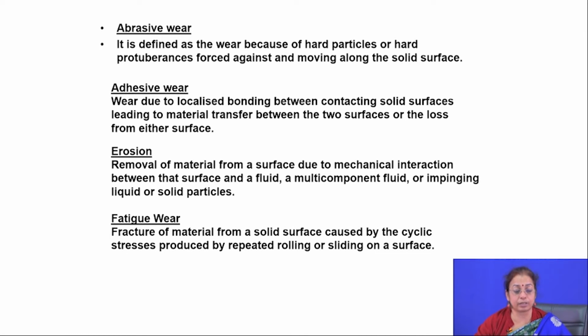Now, quickly I will go through each mode of wear as well as sub modes in this particular talk. Now, if you talk about abrasive wear, it is defined as the wear because of hard particles or hard protuberance forced against and moving along the solid surface. So, when a hard surface moves over the softer surface, you call it abrasive wear. Adhesive wear is the wear due to localized bonding between the contacting solid surfaces, leading to material transfer between the two surfaces or the loss from either side.